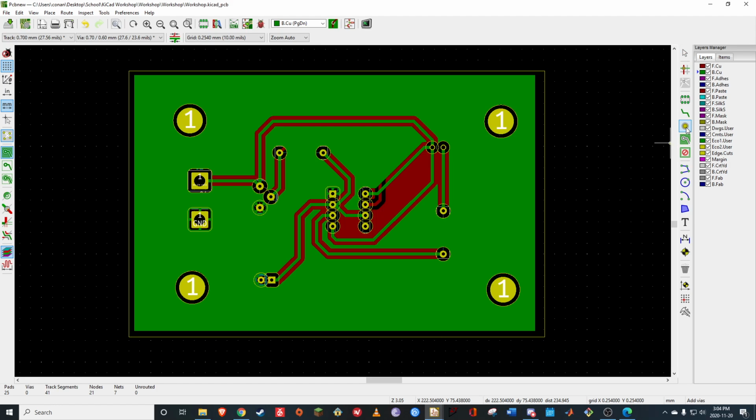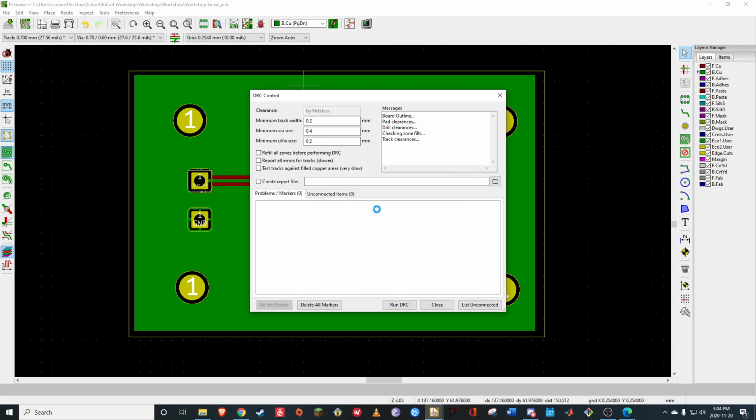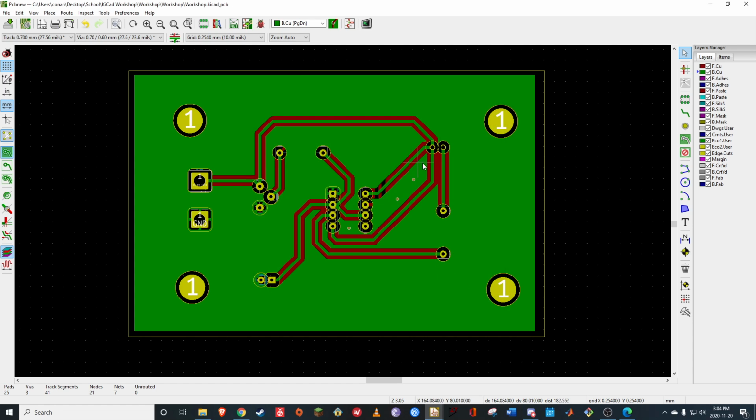To get that to pass through, you need to come over here to the right and add vias. So just add a couple in there. That's going to put a physical hole through the board so that when this gets milled, both sides get filled with the copper. Because it doesn't fill it on both sides, it needs through holes to actually get there. And now you'll see that if we run this again, now this is all filled in because our vias actually allowed the copper to flow through.